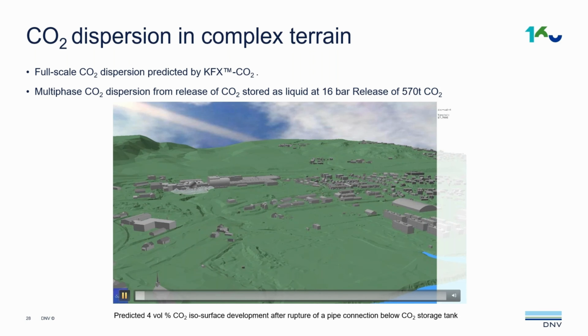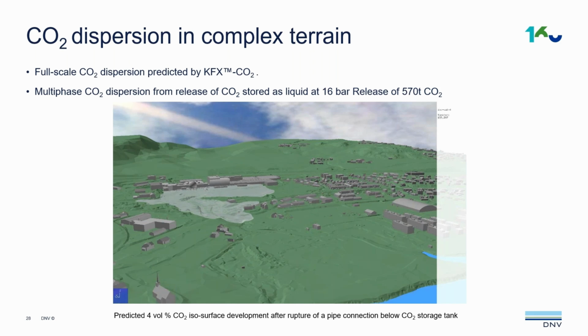So we used KFX to model this scenario. And what we can see is the 4% concentration ISO surface of the CO2 cloud. The dry ice particles sublime during the dispersion process, cooling down the cloud and making it even heavier. This has also been observed in experiments we have compared it with.